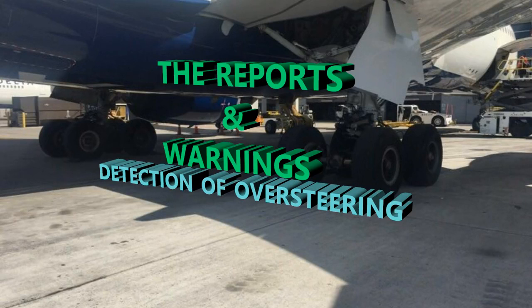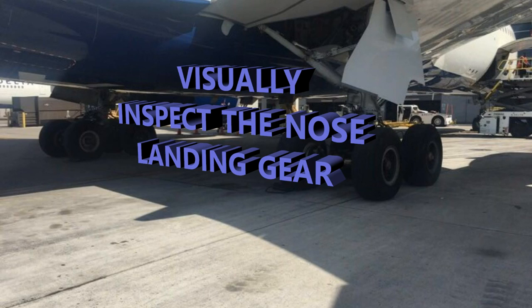You've got the alerts that are going to show up on the warning display, and also there's going to be a generation of reports from the aircraft condition monitoring system, and then you have indications to the ground crew. Of course, you need to visually inspect the nose landing gear at that point. What's going to happen is those brackets are going to be just sheared off. That's the reason why they exist. And that's the indication right there that it's too much.